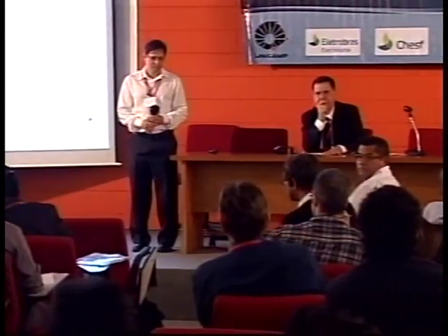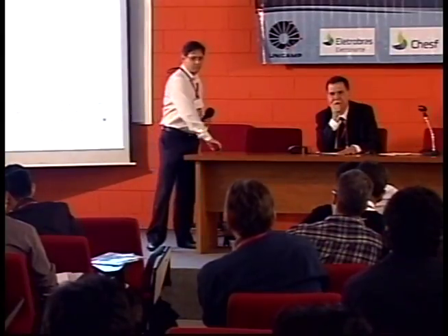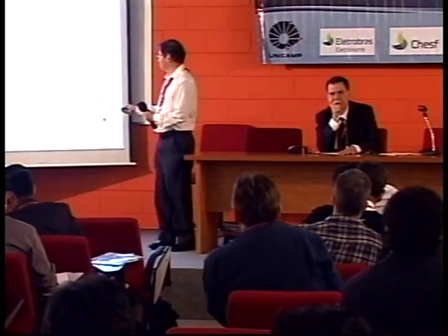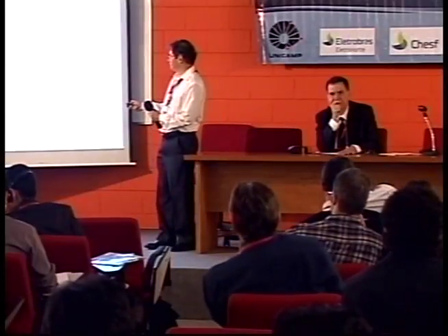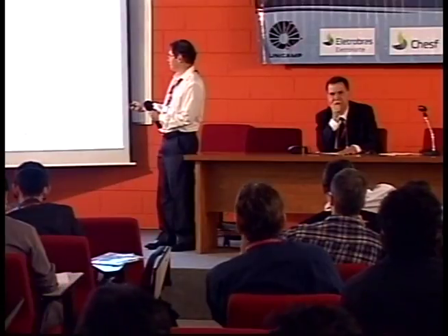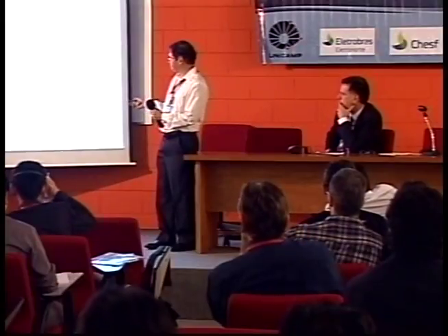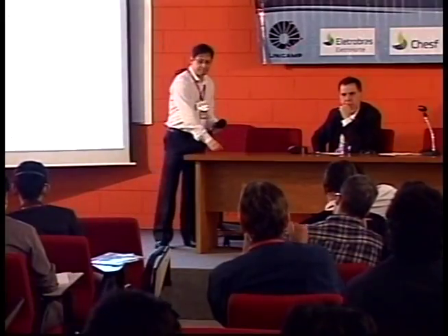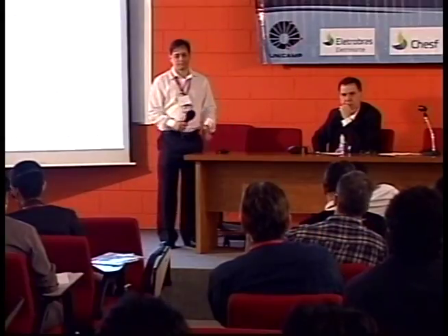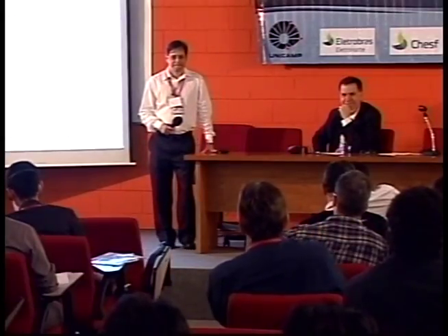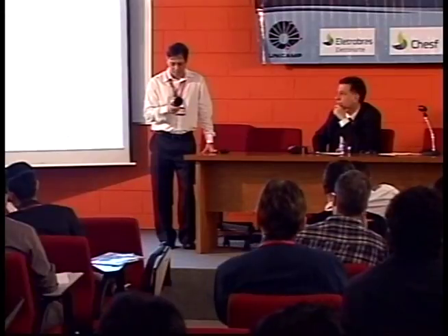Professor, in your presentation, for three-phase faults in Serra da Mesa, the ATP results were different from the PSCAD results, especially in the currents, with a difference of 1 kiloampere between one tool and the other. Can we attribute these differences to the model of the machine used in ATP or PSCAD, or do you have another reason for that?